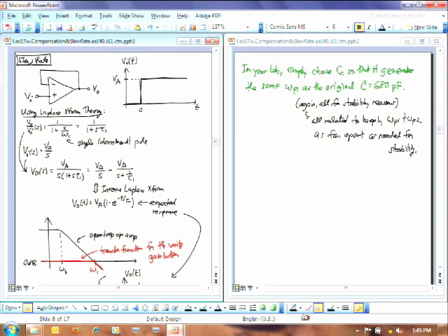So I've got this in Laplace transform theory. But basically, the easiest way to solve this problem is just to represent the transfer function of this, which we already do anyway. When we derive the transfer function of our op-amps, we're basically deriving a Laplace transform based transfer function. So the transfer function, say V naught over Vi, could be 1 over 1 plus S over omega 1, where omega 1 is, we're assuming, a single dominant pole. I can also write this as 1 over 1 plus S times tau 1, where tau 1 is the time constant equal to 1 over omega 1.